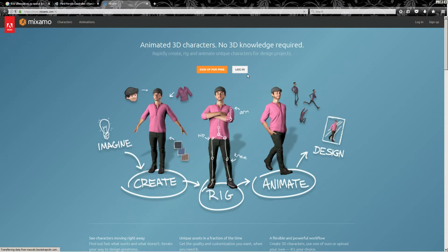Another thing is it's hard to get my object into a T-pose, and if there's another way, I'm happy and open-minded to hear how you would get him into a really good T-pose. But what works best for the system is to have him in a T-pose because it automatically generates a ragdoll. For box colliders, sphere colliders, anything that you attach to a bone, you're going to want it in a T-pose because it's easier for Unity's scaling parameters to articulate something that's not on an angle, if that makes any sense.